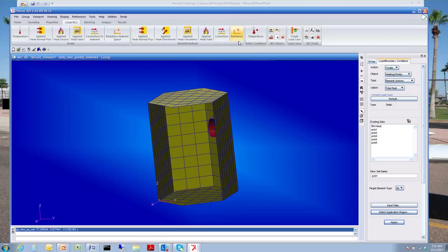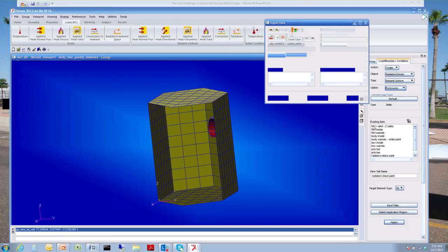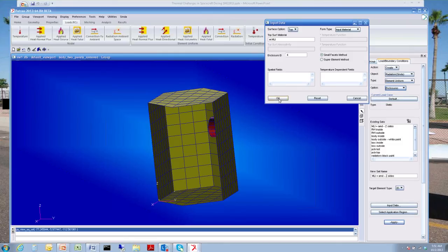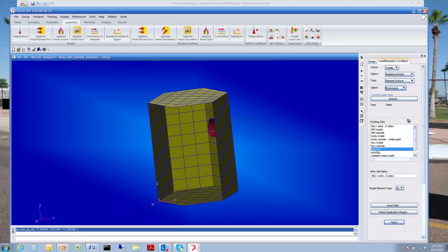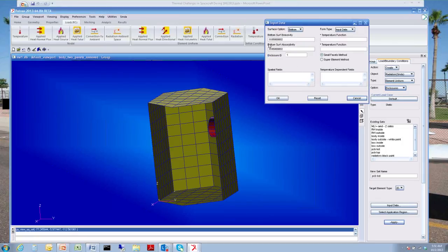And when you look at your radiation load, you only have to come in here and look at this MLI load, we just pick the material. We said we're using material, we picked the MLI material that was defined, and we use that instead of specifying an alpha and an epsilon like we might specify on another part here where I've specified an alpha and an epsilon right here.